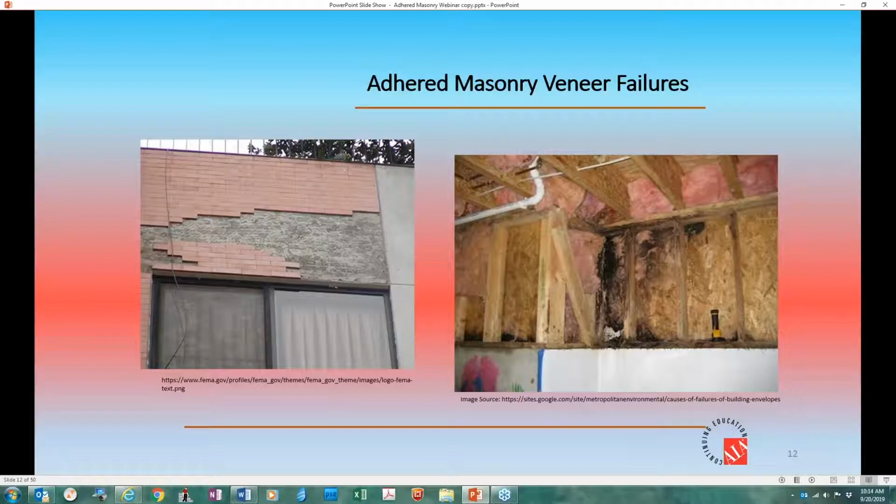There's a failure in the left-hand picture that's different from the right-hand picture here. If moisture was able to drain out of this system at a rapid rate during cold weather, you wouldn't have had the spalling that is shown. The spalling shows where the brick basically pops off because the scratch coat stayed very wet and allowed for the expansion of the moisture. If drainage was to occur behind, that would have dried faster, allowing for a more secure bond and a better scratch coat all in all.